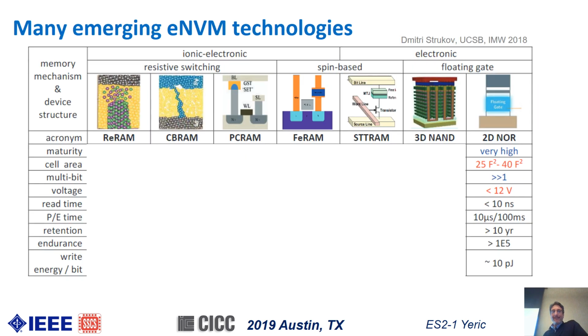Okay, so the next technology piece that's important more than more is all of the various potential new non-volatile memories that are coming out. So we have, for the last, whatever it's been, 30 years, one embedded memory. And it's a really horrible, stupid memory, right? This floating gate stuff is a really horrible memory, but it's the only one we have. It really looks horrible from a design standpoint. It's slow, power hungry. You've got to do high voltage wells, all kinds of weird problems.